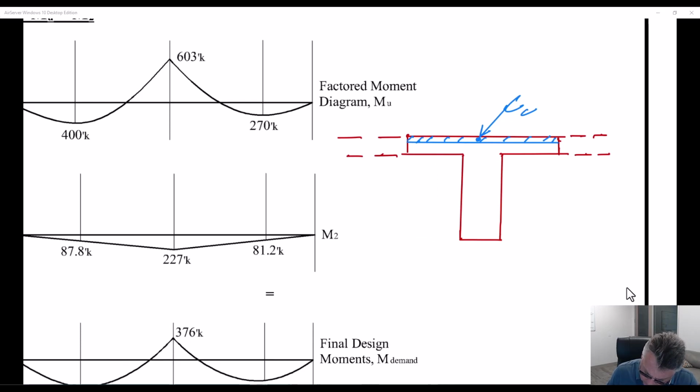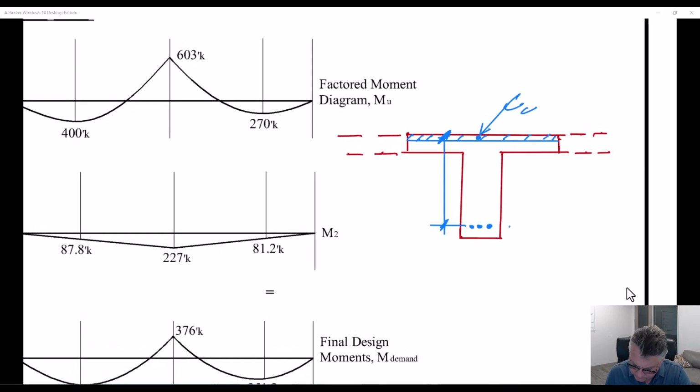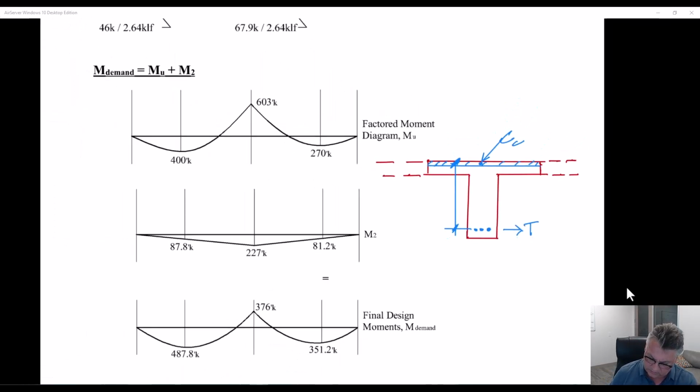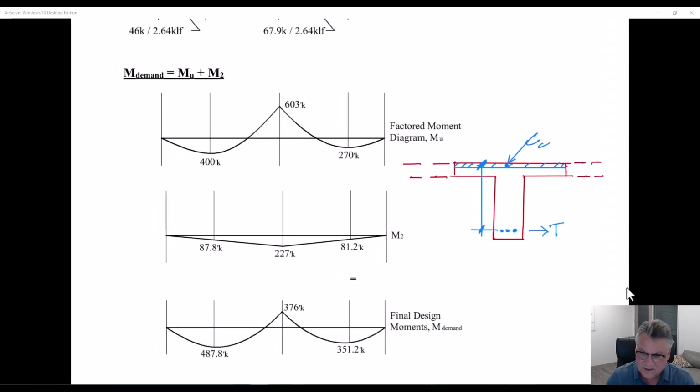Between the tension steel and the compression, the T and C couple between these two was the greatest. That was the greatest arm. That's going to give us the best capacity. In other words, in positive bending, where tension is at the bottom of the beam, it's a very efficient section, and we kind of went over that already.